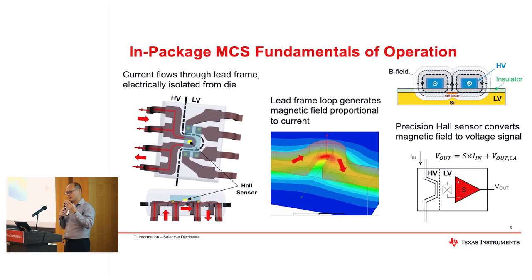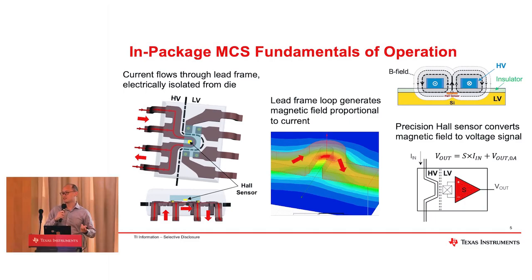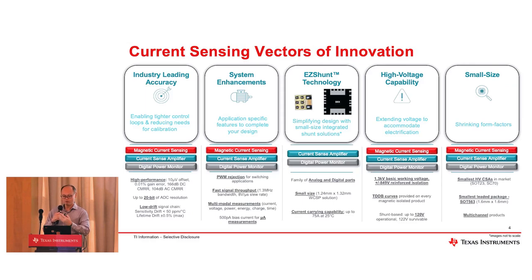So this is a series of products from TI called the magnetic current sensors. To remember, it's very easy. It's called TI magnetic current sensor, TMCS. We have functional isolation, basic isolation in a SOIC 8 package to measure up to 30 amps. If you need more, we have the TMCS1123 to measure up to 80 amps, with our reinforced isolation in a SOIC 16 package.